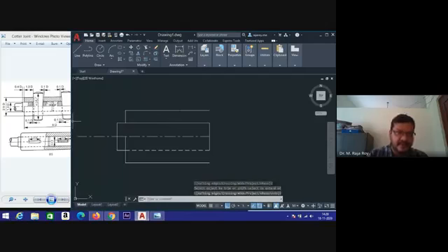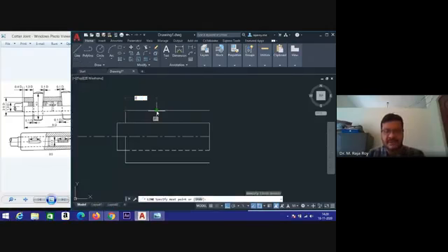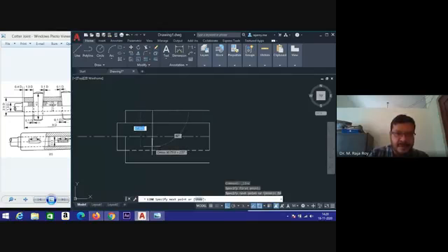Now here we have to draw the Cotter. This Cotter part you have to draw. That Cotter starts at a distance of 1.3D. 1.3 into 30, that value is 39. You just go to 39 distance from here. Then draw a vertical line like this.